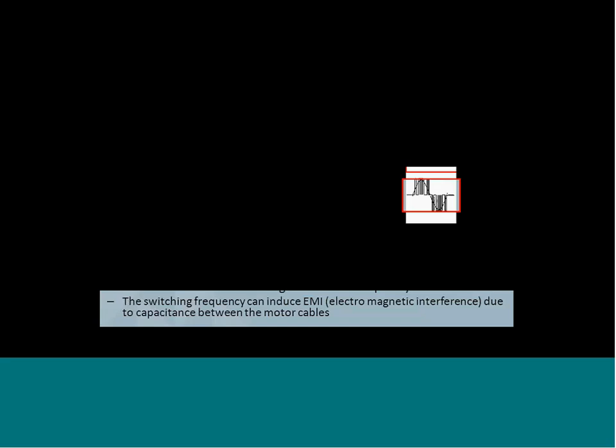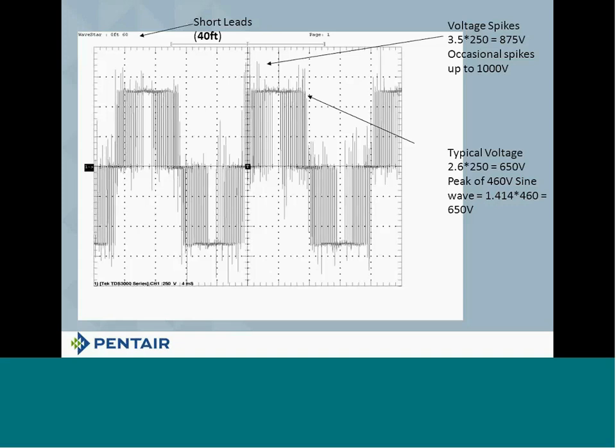Okay? So if you watch my sine wave here, you're going to see we're doing this at 250 volts in 4 milliseconds. That's what this picture is. Basically what we did was we took a 40-foot lead and we hooked it up to the drive, and then we hooked it up to an oscilloscope. And these are pictures that come right off of the oscilloscope.